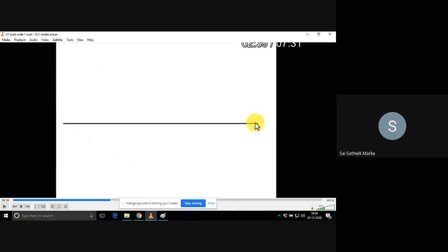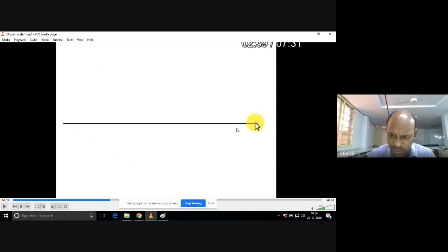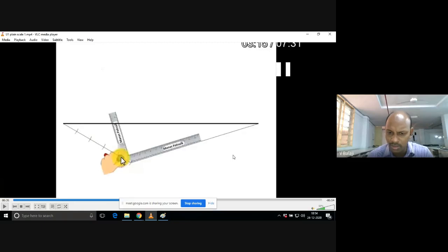Yes. Now, after drawing this 12.5 centimeter long line, divide this into 5 equal parts. You know the procedure, right? You draw any angular line, draw 5 equal arcs on that. The last arc you need to join to the other end of the line. Now match your mini drafter scale parallel to this longer line, along the longer edge, and tighten the mini drafter knob.